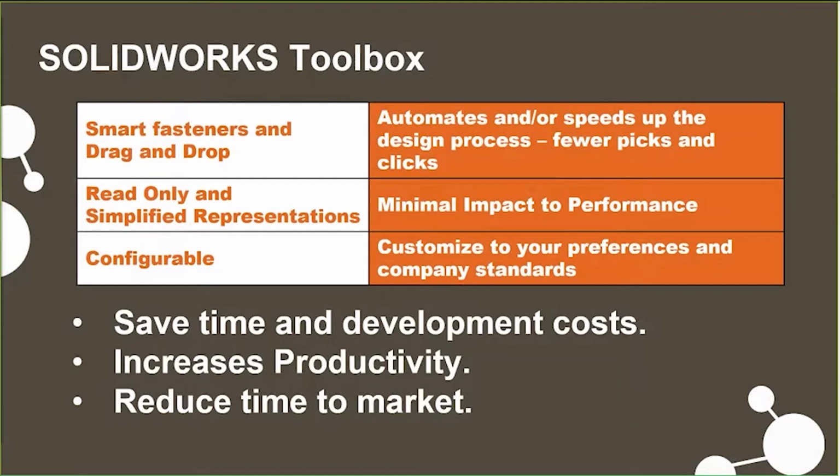So to recap, SOLIDWORKS Toolbox is fully integrated with SOLIDWORKS Professional software. It allows us to use smart fasteners and drag and drop standard components, speeding up the design process. The components are created as simplified representations with minimal impact to your assembly performance. The toolbox can be configured to your preferences and protected to your company policies. All of this is going to save you time, it's going to save you money, and you'll get your product out the door sooner. Okay, so next up is PDM.